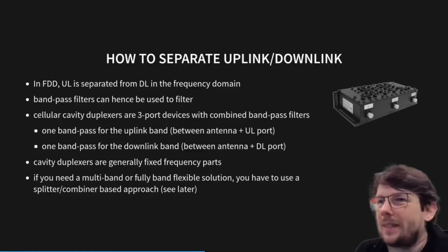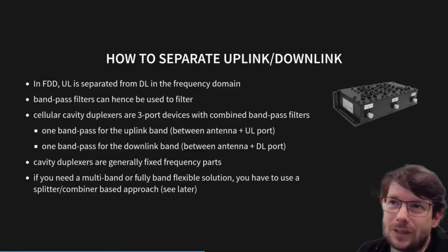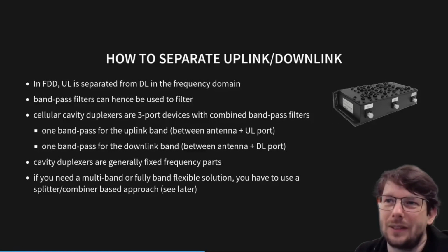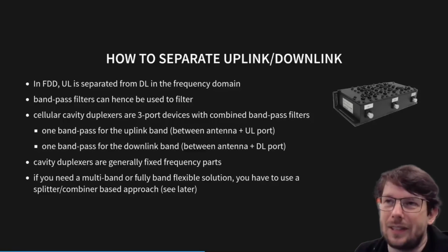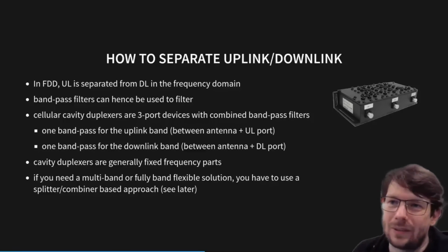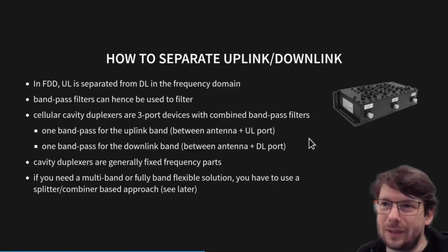The cavity duplexers are for a fixed frequency band, so you cannot use them in a multi-band approach. So if you want to build a test setup that always tests in 1 single frequency band, you are able to use such duplexers. But if you need something that's agile frequency-wise or operates in multiple bands, then you cannot use a duplexer because it's a single band device. You have to come up with a more complex solution or work with splitter combiners. There will be a separate slide about this.